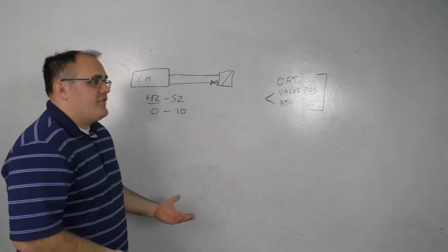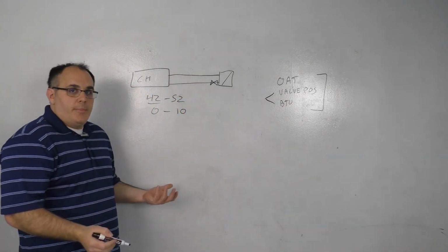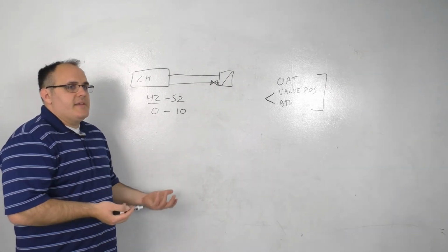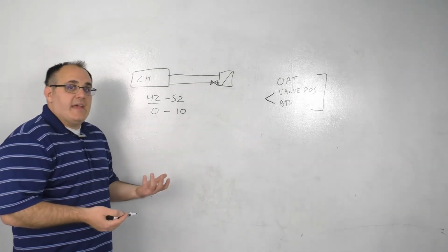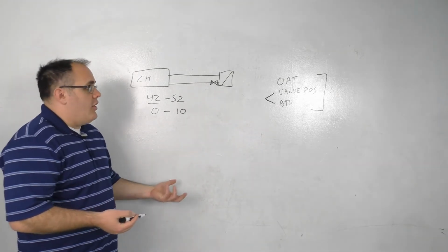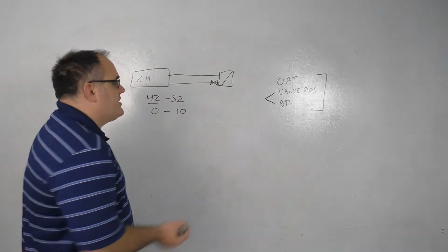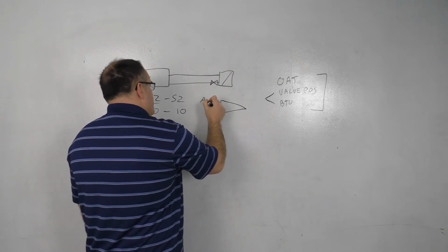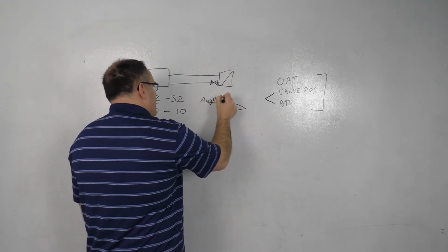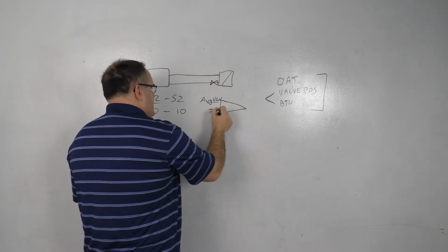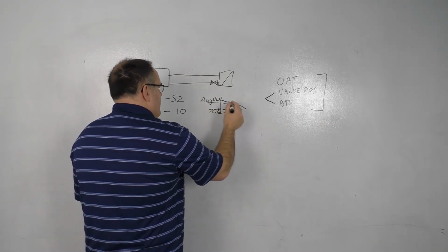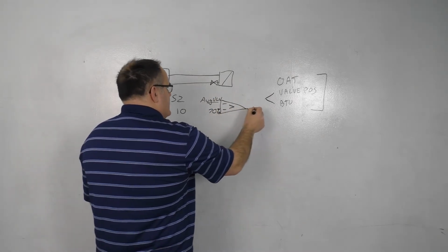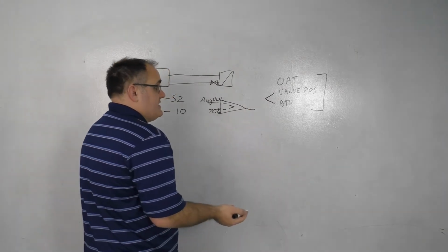Valve position, so average valve position. If all your valves are open, that indicates that your coils are flowing water through them because your coils are needing to have chilled water. So as you reach above a certain position, you would basically use a comparator block, and you would take average valve, and then you would say, maybe we want to say 70%. So if our average valve is greater than 70%, then we send through an increase in temperature.